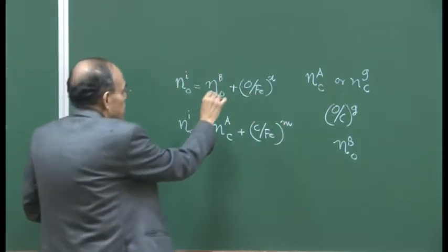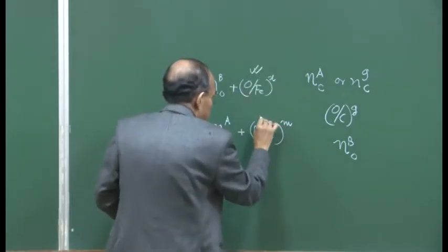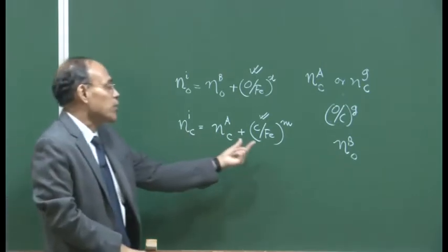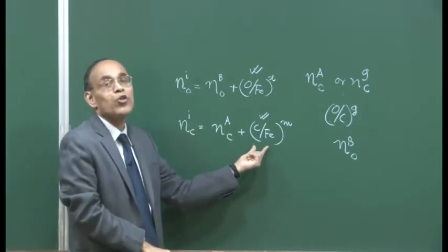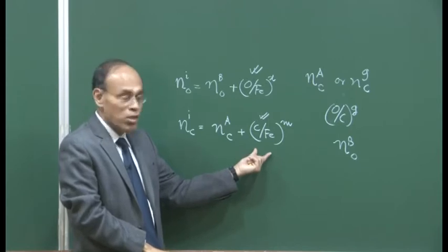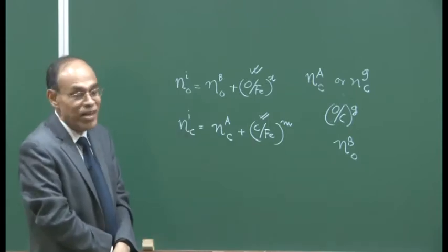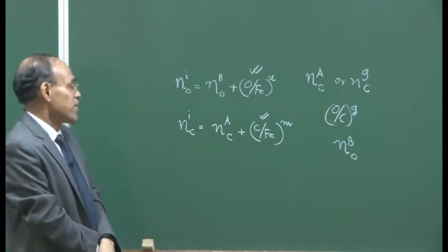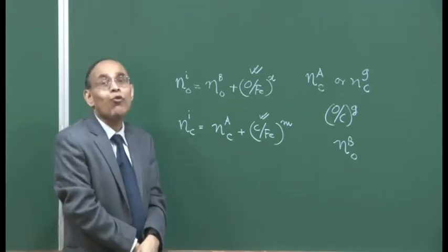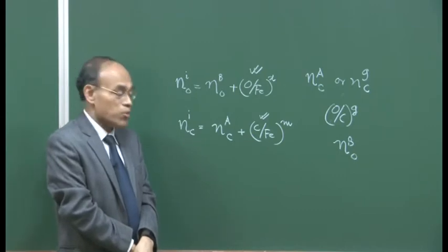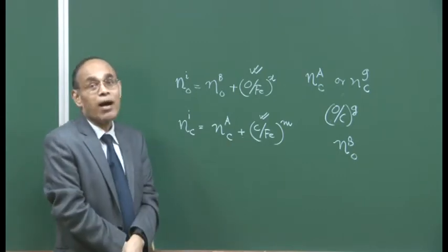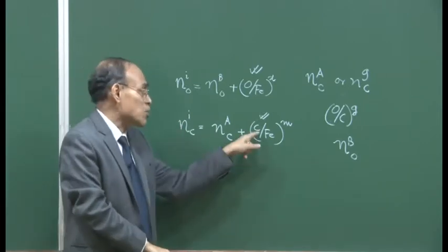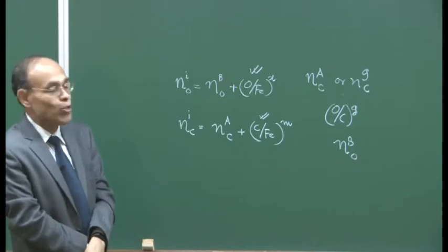Since this parameter is known and this parameter is known, this is given to be varying between 0.20 to 0.24 depending on the composition of the hot metal. I told you yesterday that if you disregard silicon etc. in the hot metal and assume 4.3 weight percentage carbon dissolved in iron, then C by Fe for carbon-saturated hot metal containing no other impurities comes out to be 0.21.